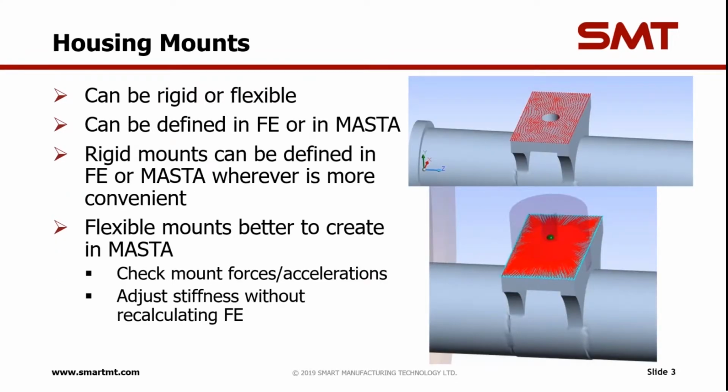So housing mounts. There's various ways of grounding your housing in MASTA. You can have rigid mounts or flexible mounts, and these can in turn be either defined in your FE program before you bring it into MASTA, or you can define them in MASTA itself if you have brought the full mesh in. For rigid mounts, you can define these wherever you find easiest, either in your FE or in MASTA. There's not any difference in what result you'll get.